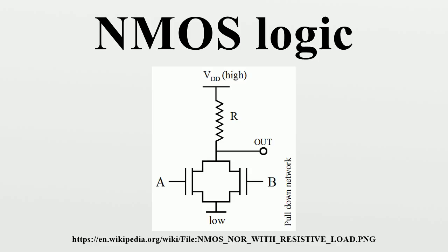However, older and/or slower static CMOS circuits used for ASICs, SRAM etc. typically have very low static power consumption. Additionally, just like in DTL, TTL and ECL etc., the asymmetric input logic levels make nMOS and PMOS circuits more susceptible to noise than CMOS. These disadvantages are why CMOS logic now has supplanted most of these types in most high-speed digital circuits such as microprocessors.